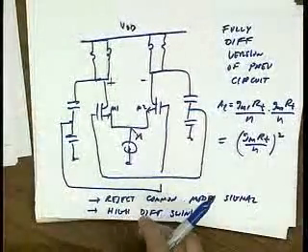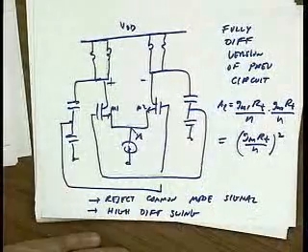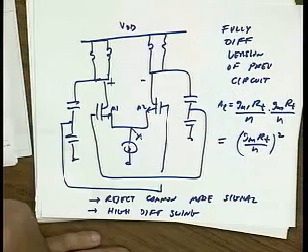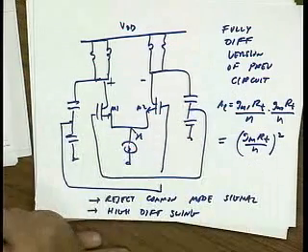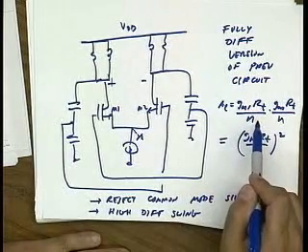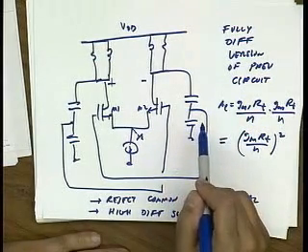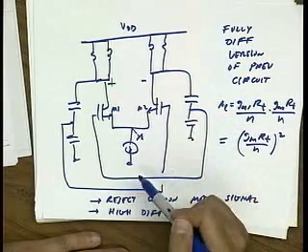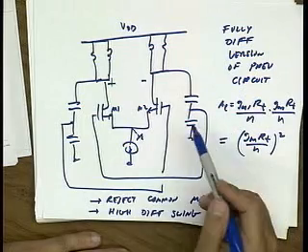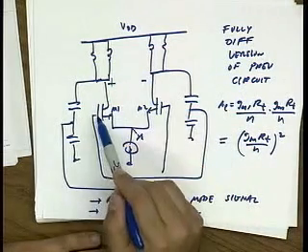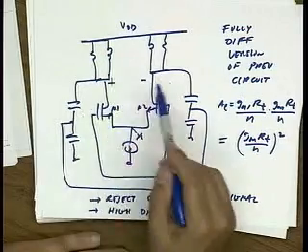Also notice that in this circuit, if I want to maximize the loop gain and minimize the current consumption, I should really set this feedback factor to 1, right? Because I'm losing gain by having a feedback factor. So if I just set that feedback factor to 1, that would be equivalent to basically eliminating this capacitor, right? But the DC level here is very compatible with the DC level here. So what I can do is actually directly connect these 2 points. I don't even need to use a capacitor.